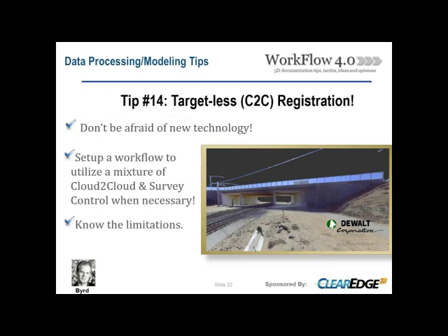Yeah, I threw one in here during the data processing. So target list registration, I know we've also talked about it a little already, but my first comment for it is don't be afraid of it. Don't be afraid to try new technology. Get into the software that's utilizing it and trial it and test it. Whether it's a project you've done in the past and you want to take those same scans in and try the target list, or you want to do it on your next project, it's worth trying, because if you set it up in a proper workflow, you can use a mix of cloud to cloud and survey control, or cloud and cloud and a few targets, but you do have to understand the limitations.